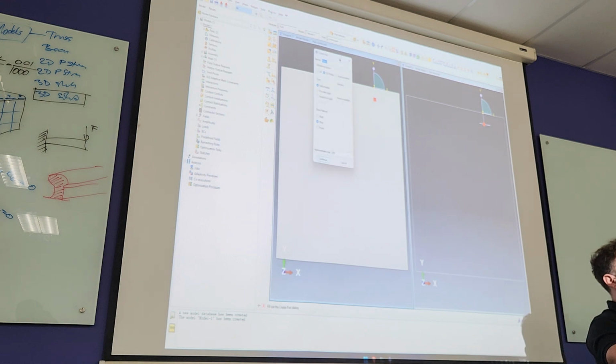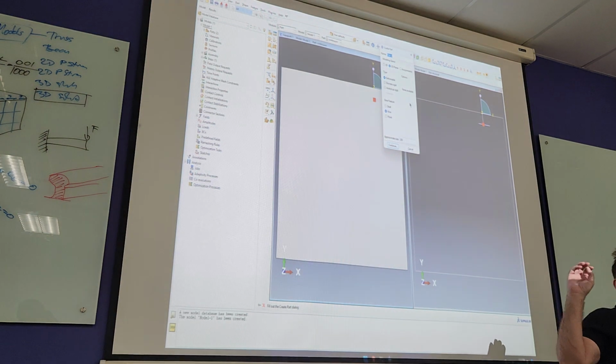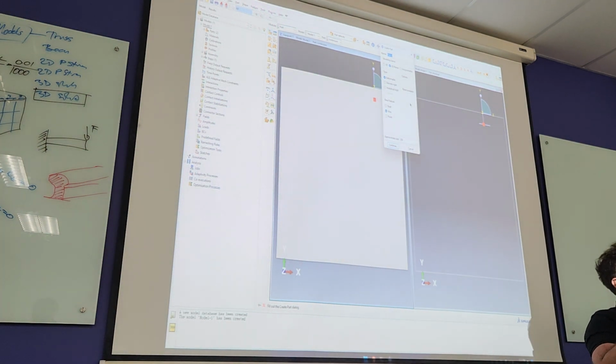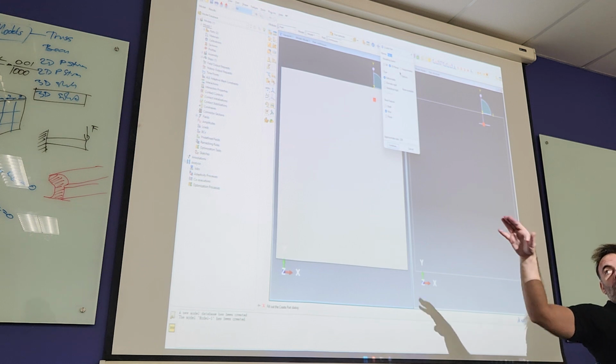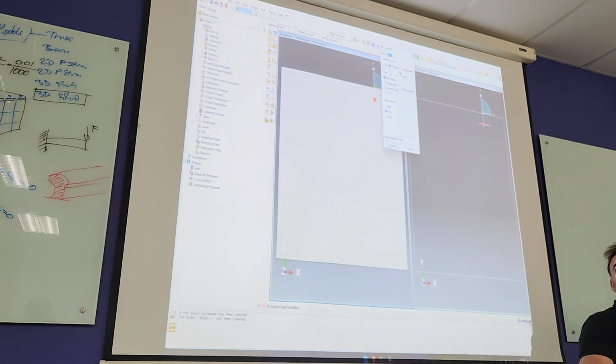When it comes to creating the parts in Abaqus, there are different ways Abaqus creates that material, and that is defined here. So first we are defining what sort of modeling space we are dealing with. Is it 3D space or 2D space? It's going to be 3D space. That means all above, so truss, beams, 2D solid, they can be modeled in that space. So nothing exists in third direction.